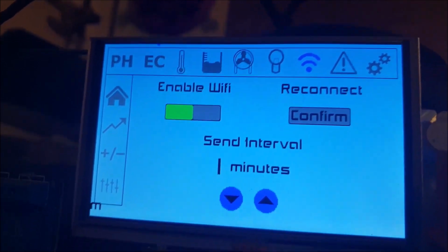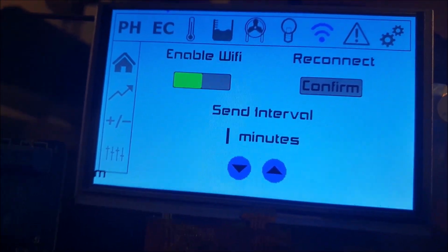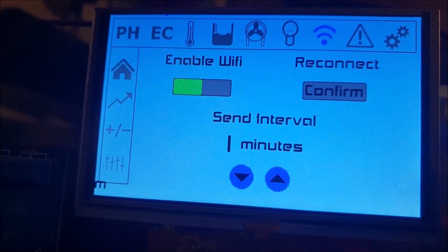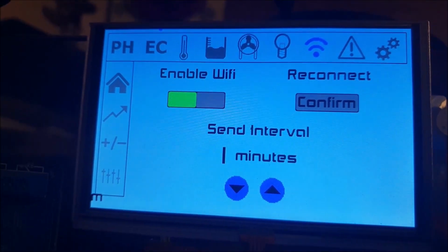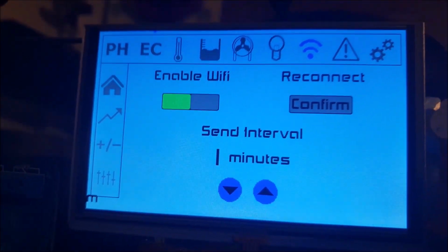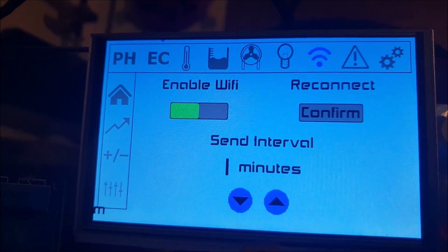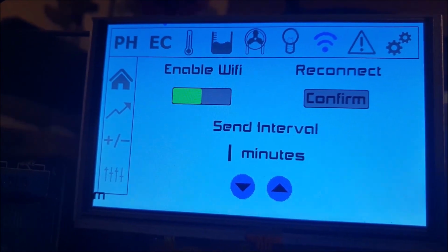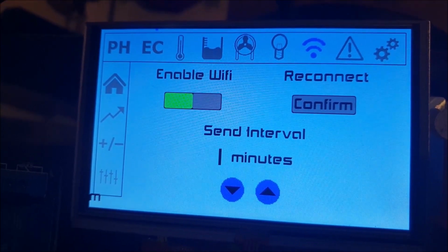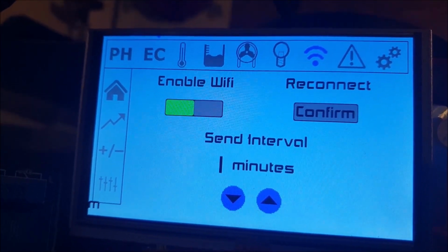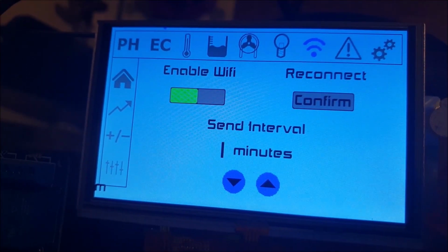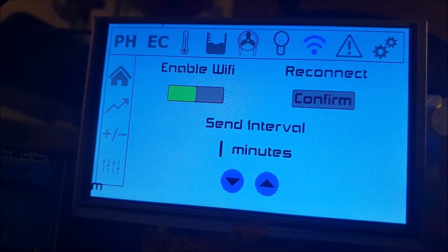So it's taking the current reading, the next reading, working out how much it's adjusted it, for each reading with a precision of 0.1, and then later down the line it can load that recording, say it adjusted it by this much, work out the current gap between the sensor and the set point, and then multiply the dosing accordingly, be it up or down. So let's say the multiplier comes out at 0.1 and the value is 5, then obviously that would be 0.5.